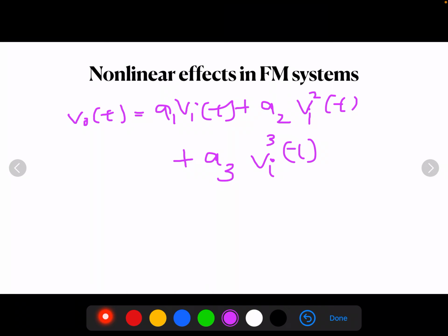The second version is weak nonlinearity, when a linear performance is desired, but nonlinearities also arise due to imperfections. The effect of such weak nonlinearity is that it limits the useful signal levels in a system. So it becomes a design consideration. You have to consider it and you have to get rid of it.